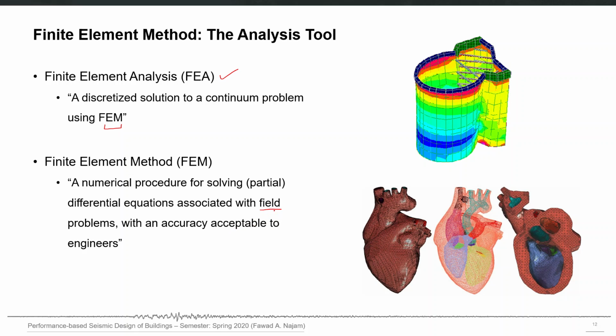In our case, the field will be the displacement of our structures. So the field is the displacement, and we are required to calculate this displacement against any given excitation or loading for our structure, and we will divide our structure into simple elements which we will call finite elements.